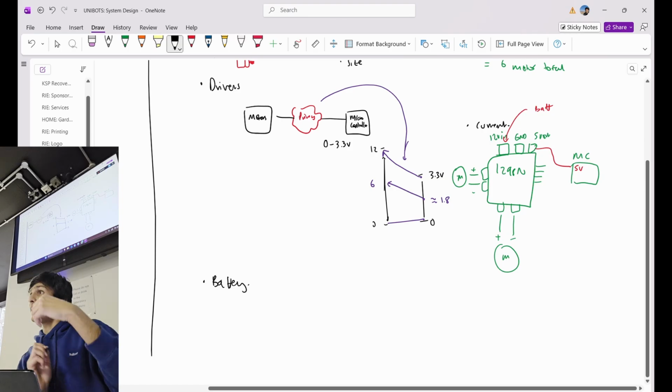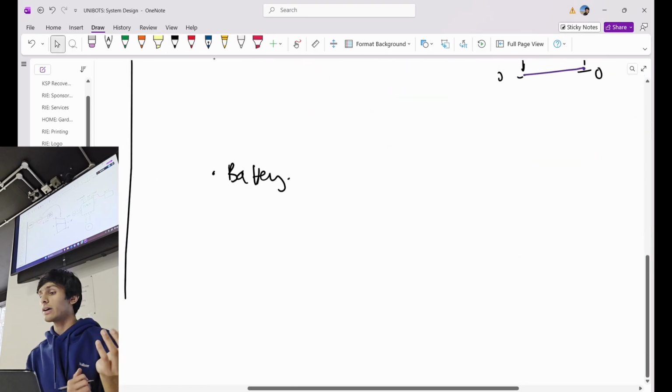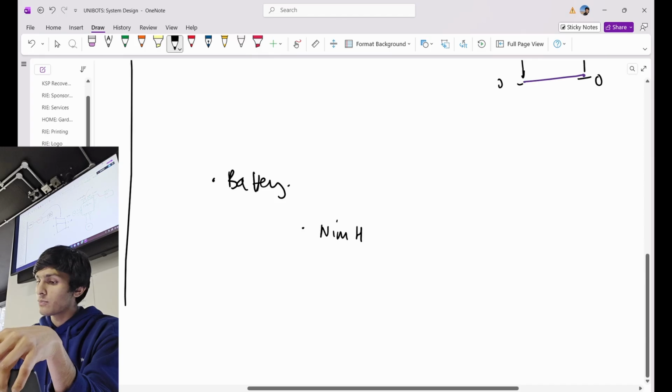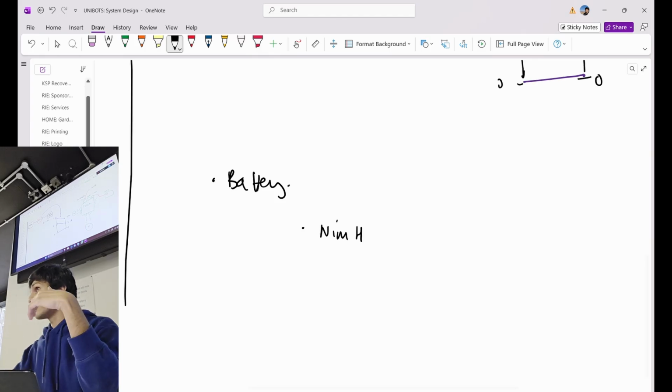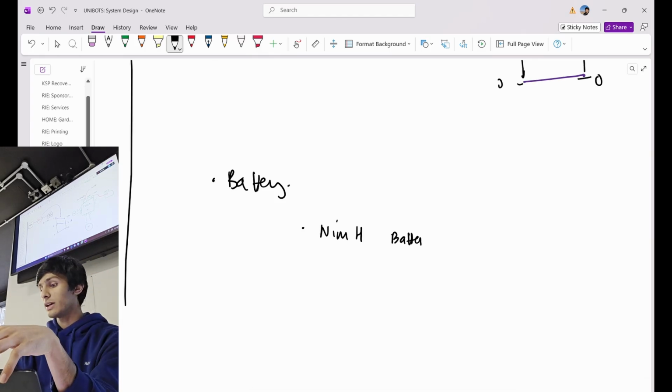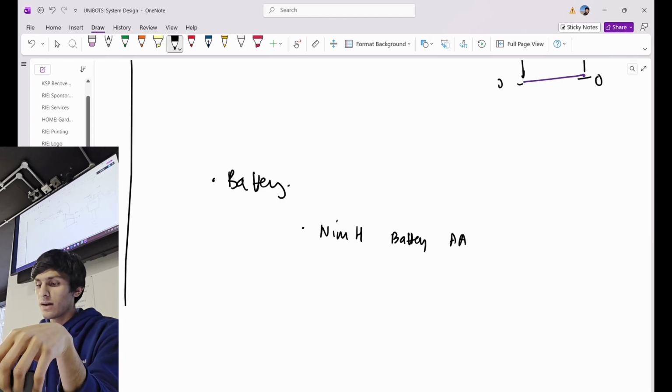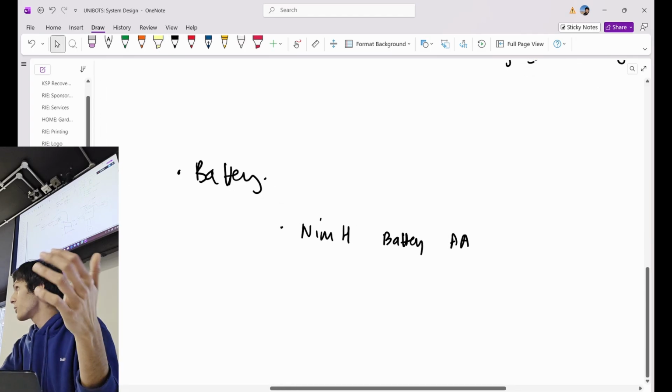directly from the L298N, which I've found quite useful because it means you don't have to have this microcontroller work at 5 volts. It means I can put the battery in here, and it will automatically do the voltage conversion in here to give me enough voltage for the Raspberry Pi, for the ESP, whatever I want to use. It means there's one less component we have to buy.